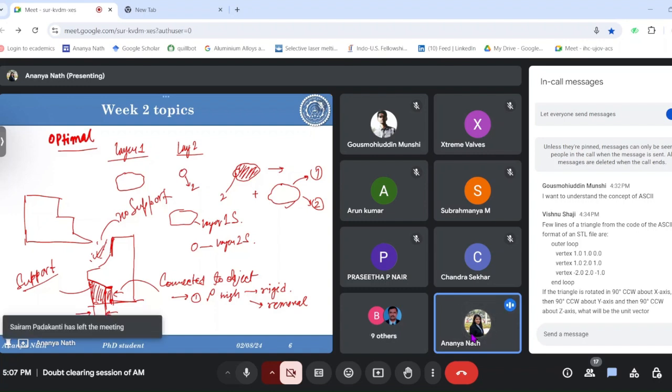But if you make low density support, like tree support or something like that, then you will hamper the rigidity of the support, because the main working of the support is to give enough strength to the overhang portion of the object. So tree-like support may not be enough for the part, but tree type supports are easy to remove. So rigid is not easy to remove, while tree is not rigid but easy to remove.